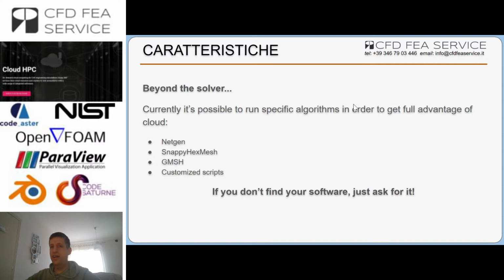Beyond the solver, as we saw so far, it is possible to run OpenFOAM, Code_Saturne, and FDS, but many other solvers. It is also possible to run customized scripts, okay? So all your Bash or Python scripts can be executed on the web application. There is a particular feature available on the cloud, so you can do that. You just need to make sure you have configured the folders consistently with the IT system of the application. But since we are using for OpenFOAM the default installation provided by the OpenFOAM Foundation or the ESI group, I guess it's quite easy for you to create your own script and run it on the cloud.